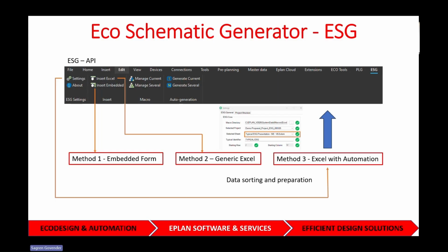You create VBA code in there. So instead of you manually going and typing the variables in there, you might have master data, you might have an IO list, you might have a motor list. So why not copy that information from that IO list or the master data into those variables? So it saves you from typing them or copying and pasting. So you're using code to actually get this done for you.